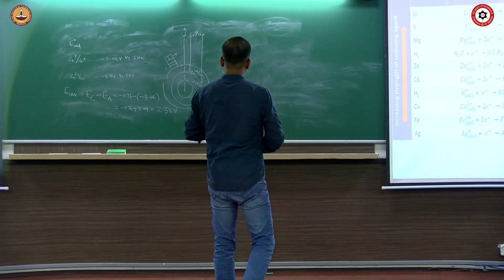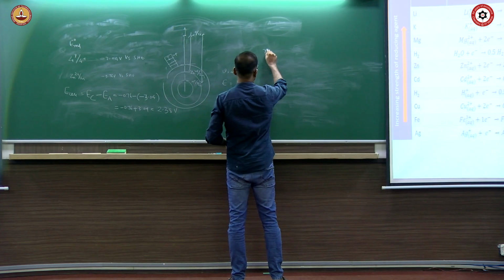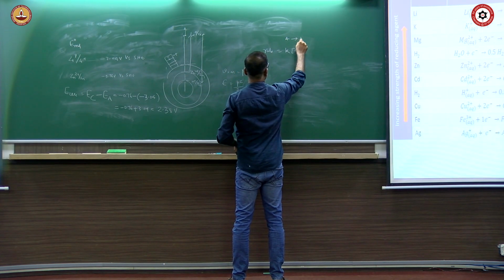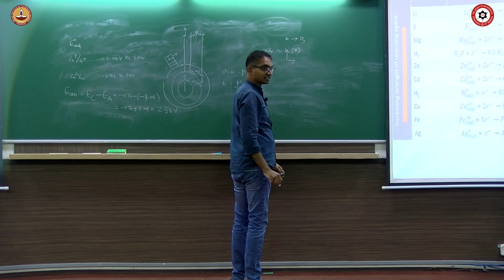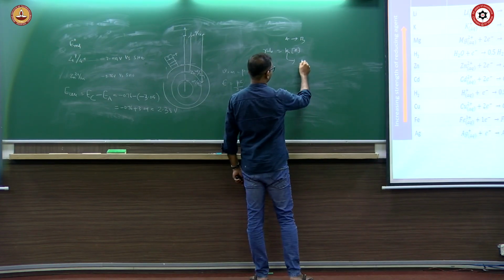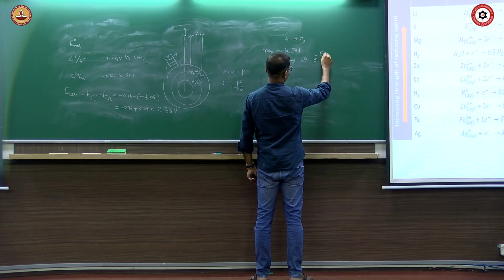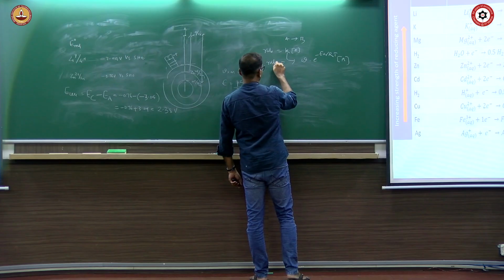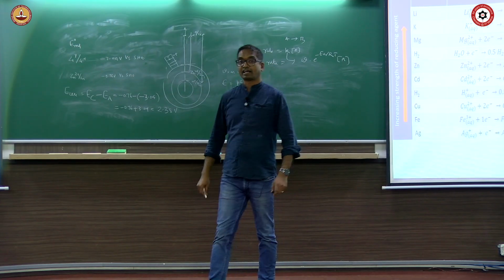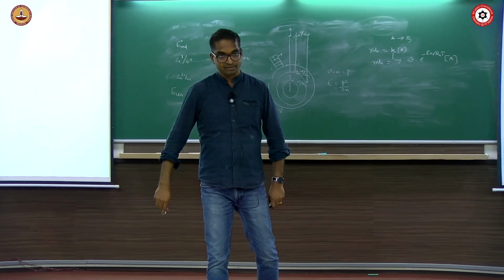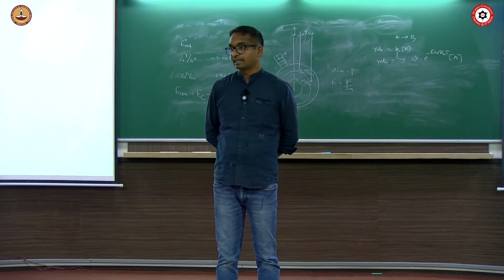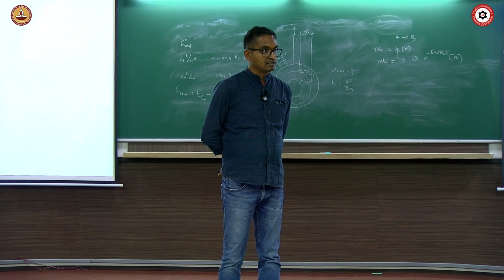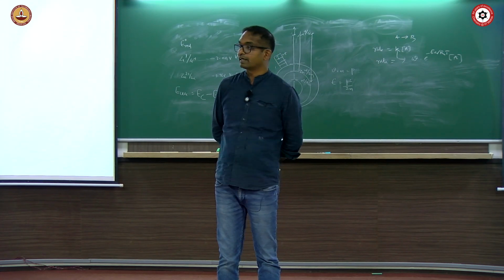So, that is what I asked in the morning when I say rate, K times A we wrote, correct? I asked how will you expand K? You did not answer me. You will expand K like this. Correct? What is that? I assumed an Arrhenius kinetics. So there is a frequency factor times e power minus activation energy by RT times the concentration. That is the rate of the reaction.